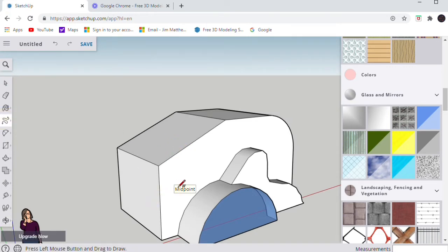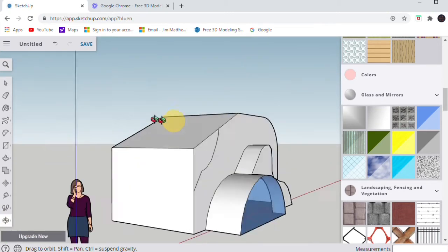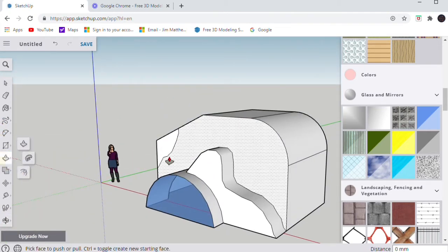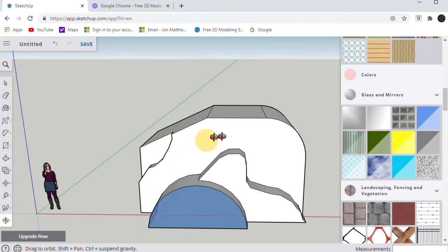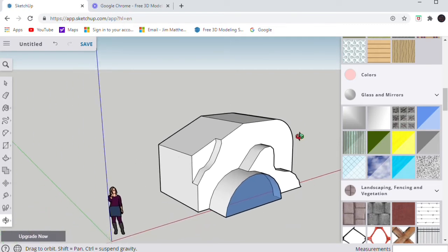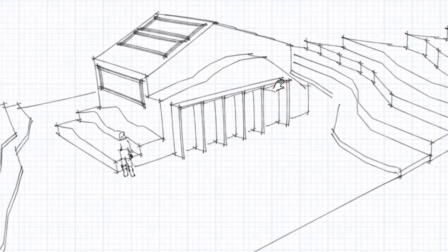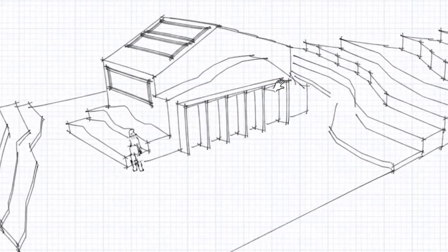But also, if you draw it correctly like this, you'll see that after you click it on, it goes to a thinner line weight. I can move and check it's flat on the surface, and that will enable me to push, pull, and extrude that shape in order to add or subtract from my three-dimensional object. So your first task is to make a login for SketchUp and have a play around with those basic tools, and then revisit the video when you are at a stage where you feel comfortable with the basic tools.